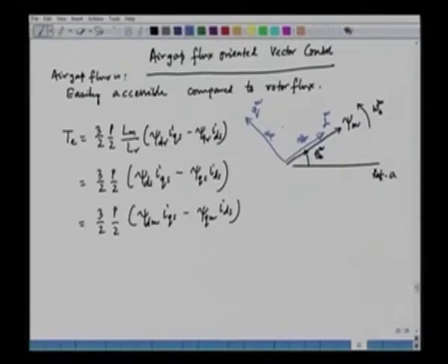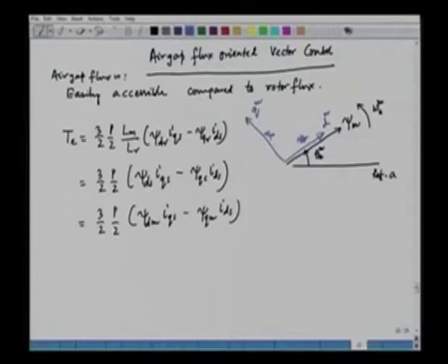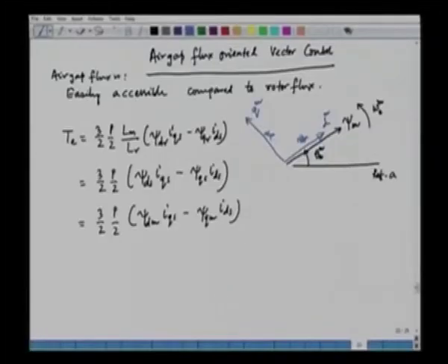And furthermore, you know that this reference frame is rotating synchronously with the air gap flux vector. So we add a superscript here. We can say that that's equal to psi dm and psi qm, and the currents will be iqs m and ids m. The superscript m shows that these are special variables. These variables are all defined in a hypothetical reference frame rotating with the air gap flux vector.